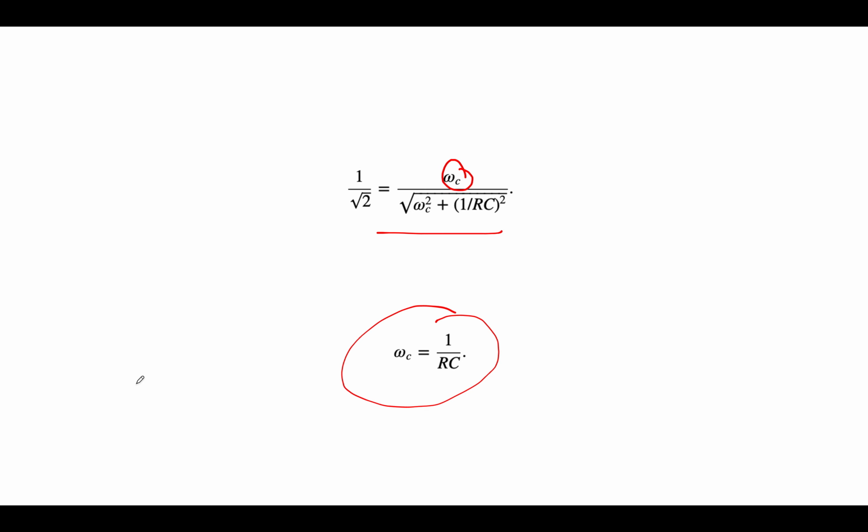The thing that's different in the transfer function is what the numerator looks like. The cutoff frequency and the behavior in the time domain as far as analytical function are similar, but the fact that you have an S term in the numerator of the transfer function changes everything and takes what would have been a low-pass filter and changes it to a high-pass filter.